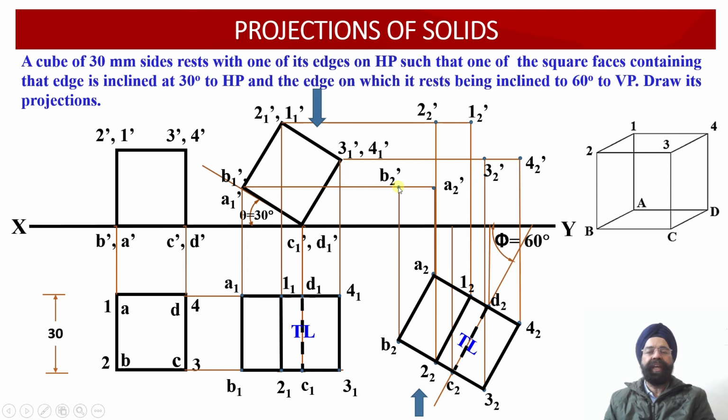be located over here. And finally, this is the horizontal projector line drawn through the points C1 dash and D1 dash, which are located onto the horizontal plane. So let us work out the intersection of the horizontal locus line drawn through C1 dash and D1 dash with the vertical projector line drawn through C2 and D2 over here. You can check, C2 lies here, D2 lies here.